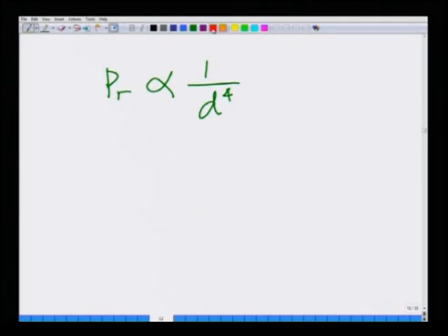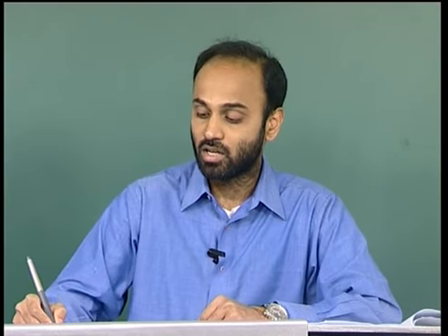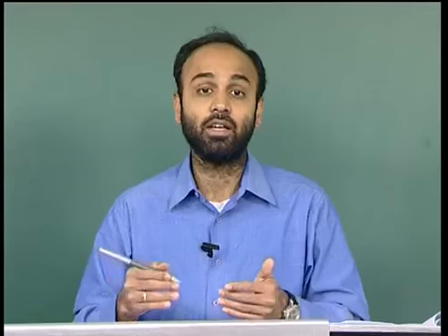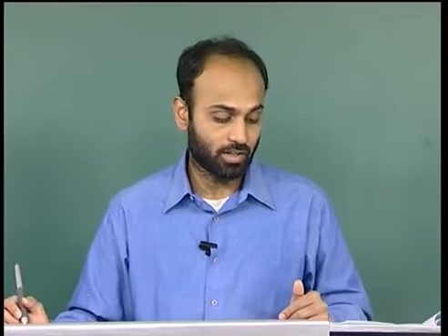This means the path loss exponent, the power now decays as the fourth power of distance. Hence, the path loss exponent equals 4. When we have obstructions, essentially when you have reflections and so on, the path loss exponent increases, which is typically what we expect in urban and cellular scenarios.